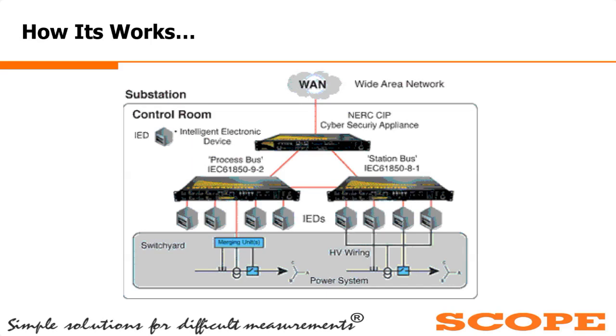For those data packets to move from one digital device to another digital device, like here in a substation environment, those IEDs, relays, BCUs are digital devices. Those are giving all the parameters like overcurrent relay status, arc fault relay status, breaker on off control, and other voltage and current parameter signals. So those signals can be transmitted to your local SCADA or to a remote SCADA through a gateway